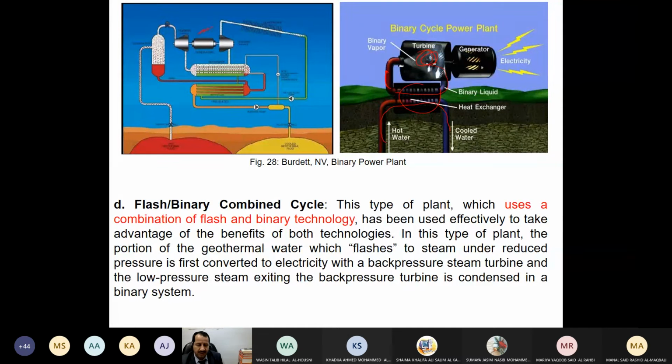And by the way, just to mention, I remember the study reported by the Authority of Electricity Regulation in 2008, the report I mentioned in some of my lectures. Their recommendation regarding geothermal was that there is no potential and the temperature is low, which is not suitable to generate electricity. That is not accurate, because there are binary systems that can use this low temperature to generate electricity.